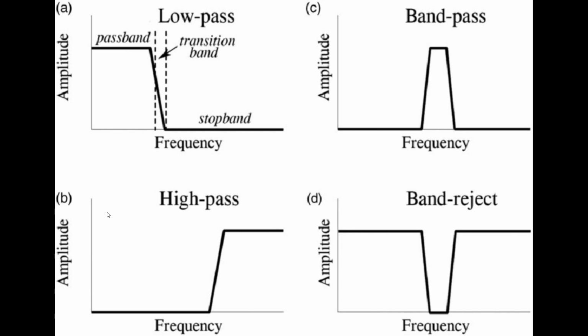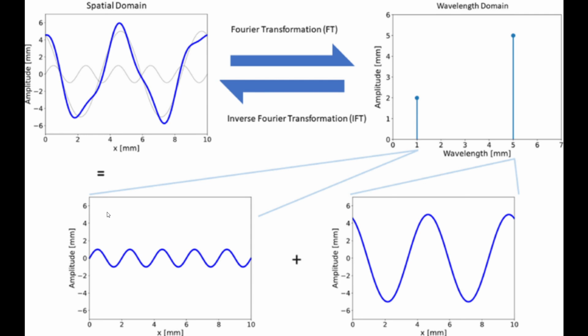After applying these frequency domain filtering operations, the inverse discrete Fourier transform, or the IDFT, is performed to convert the filtered signal back to the time domain. The IDFT allows the manipulation of the time domain signal by reconstructing it from the filtered frequency components. The result is a modified time domain signal which corresponds to the audio signal after filtering. Since the DFT and IDFT are symmetric operations, applying DFT followed by filtering and then the IDFT reconstructs a time domain signal that is altered based on the filter type chosen.